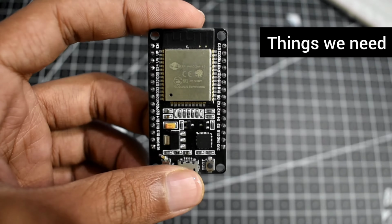Now I've added the DHT.h header file. I already have added the library before, so I'm going to show you the library manager. I'm using the DHT library by Adafruit, and I'm using a specific version since it is compatible and it works fine for me.